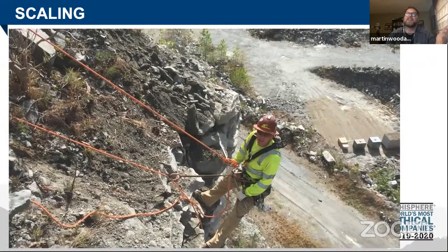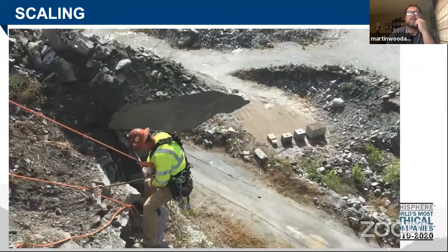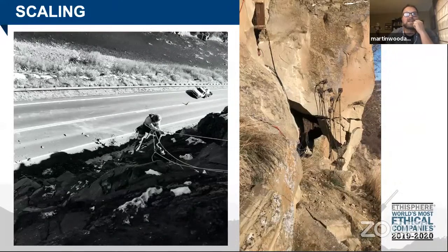So when you look at what Fred did and you start to look at that factor of safety and looking near equilibrium, that rock had to be right near equilibrium because it didn't take that much energy. You can see the size of the bar that he had when he was out there. So scaling is an act where you go and you test all those discontinuities that are in the rock. And if they move a little bit, then by definition, the rock's got to come down. They got to work it out.